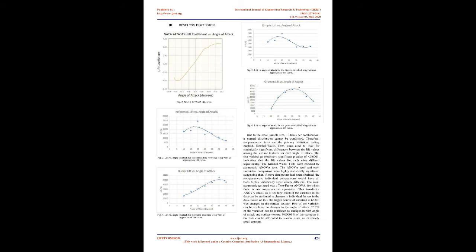3. Once the control wing was designed in SolidWorks and the surface textures were added for each wing in Fusion 360, they were exported to Autodesk CFD for analysis. Due to this experiment's targeted application of elliptical wings in real-world conditions, the environment and testing conditions were set to mimic a drone or other such aircraft flying at an altitude of approximately 8,000 meters. The analysis temperature was set to -5 degrees Celsius to account for this altitude. The test condition velocity was set to 165 m/s, the average flying speed of the General Atomics MQ-9 Reaper, a currently available unmanned military drone.